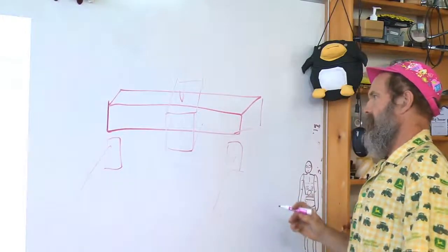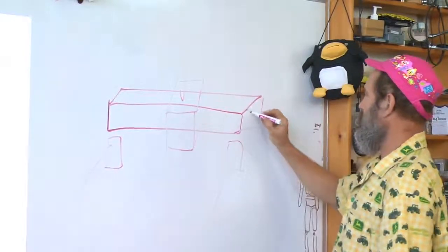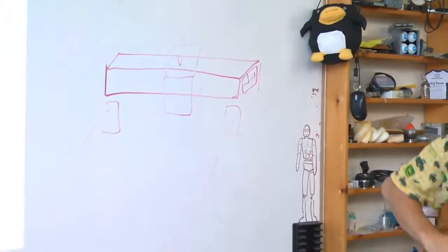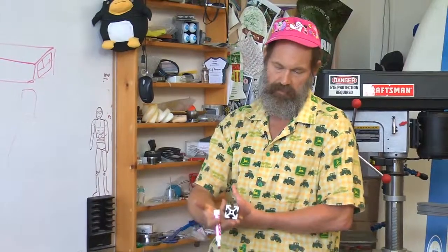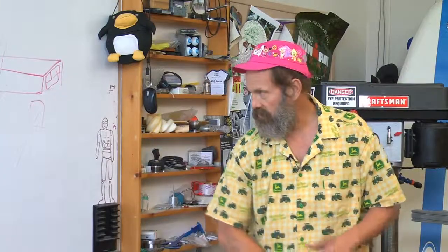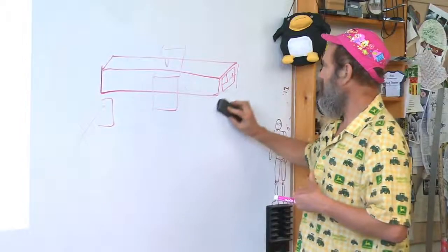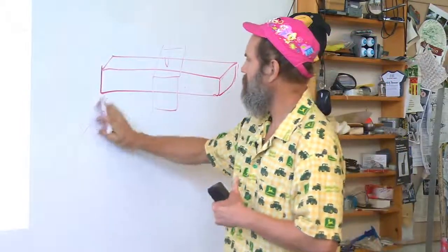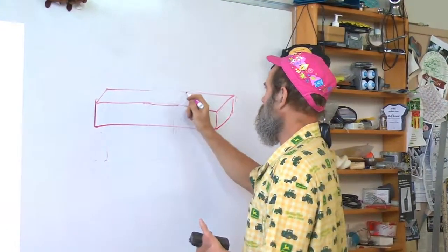And I'm looking at this beam and I want to know the deflection of the beam and the strength of the beam, and maybe I'm going to do that because this is some weird shape like we just drew earlier, this guy with the plates on it. And I did my first order analysis assuming that it's just the top and bottom plates that govern the stiffness. But I want to check it, particularly for things like torsional loading. Well, okay, I'm just going to take this beam and I'm going to load it, simply support it, load it, see what the stiffness is.